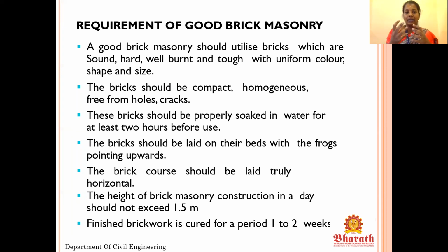The brick should be hard. It should be hard, well burnt. We generally use well burnt and tough bricks. It should be of uniform color, shape, and size. So the shape and size should be proper. The brick should be compact, homogeneous, free from holes and cracks. It's a common thing.